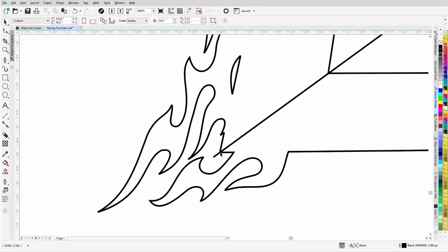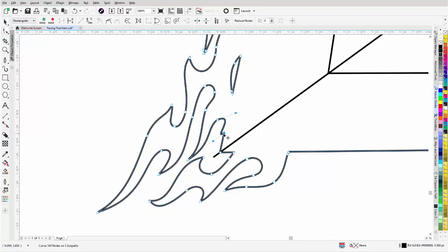And we can see places where the nodes really aren't working the way the brushes were welded into the actual numbers. So go to the pick tool, and here I can just start to delete things and make adjustments. I'll select that node, take the control arm, bring it up here, bring this control arm back, smooth that around. I'll come over here and double click here and drop a node, come here, double click and drop another node.